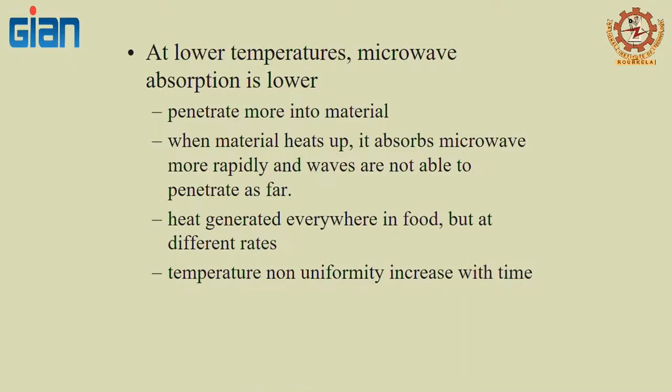The other thing that is probably going to happen, remember when we talked about electrical conductivity, we talked about how the electrical conductivity and temperature are coupled with each other. In other words, when you add certain temperature, it is going to increase the electrical conductivity, which in turn increases the heating rate and then increases the temperature. With the increasing temperature, you are going to increase the electrical conductivity and so on and so forth.